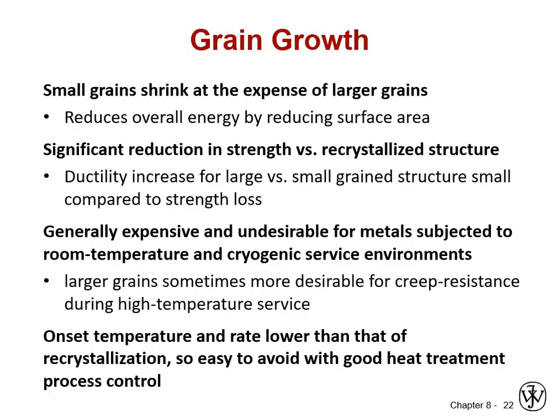Grain growth is generally universally bad in terms of properties, with the exception of high temperature creep, where we do want large grains, especially those oriented in the direction of applied stress at temperature. For everything else, small grains are better. Grain refining is a great technique for increasing strength with a small hit on fracture toughness. So we never want to leave a material in the furnace long enough to get any kind of grain growth.